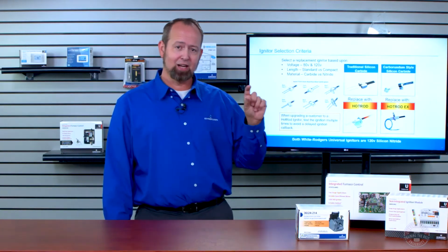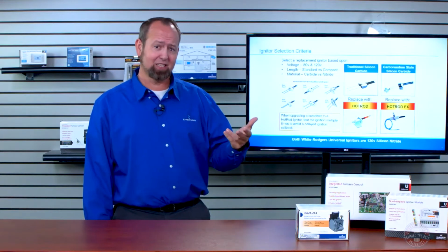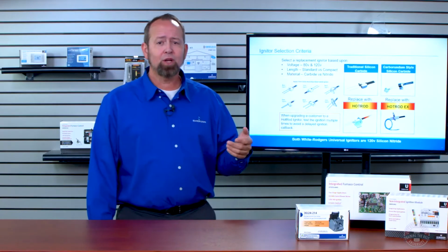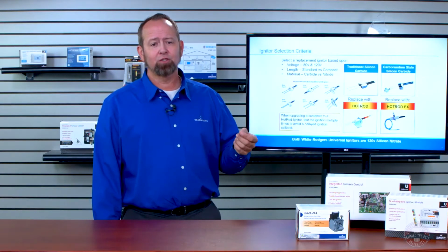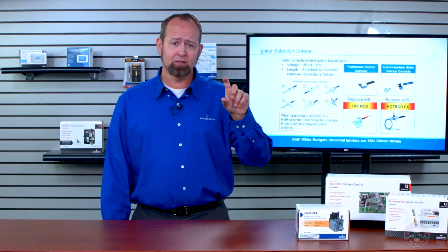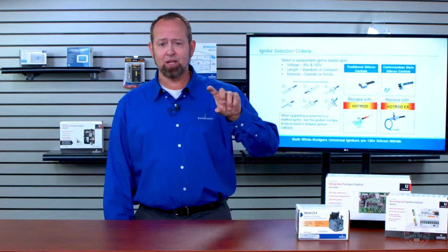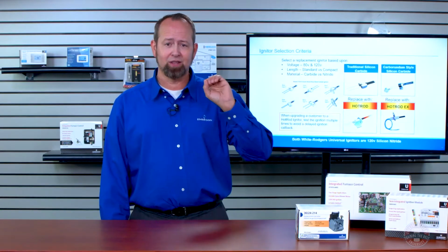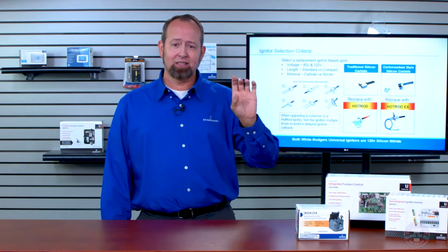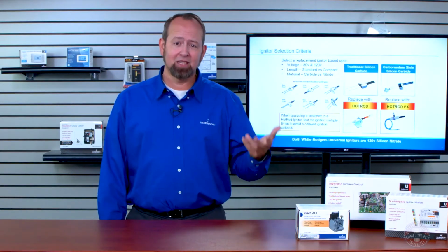You want that igniter to fall in the same spot that the old silicon carbide igniter was. And a little bit of a tip along the line of doing this: when you do this upgrade, you want to make sure that you ignite the furnace multiple times. The reason for that is, if your new igniter happens to be off or in a little different spot, when the gas comes out and it doesn't catch that igniter instantly, you can have some delayed ignition.